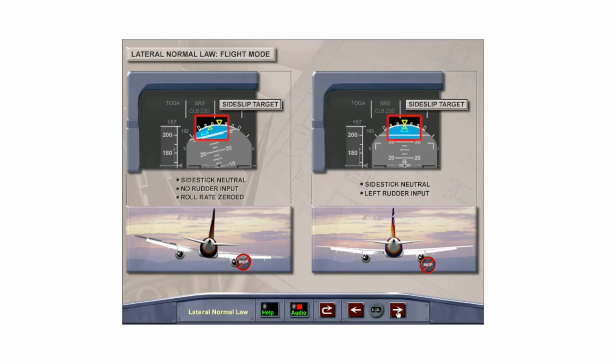To assist the pilot, a side slip target indicator is available on the PFD. The color changes from yellow to blue, with flaps at 1, 2, or 3. Pilot response is instinctive, as with a conventional slip ball: step on the target to align it with the roll index.